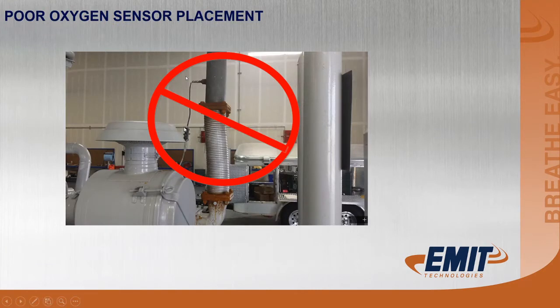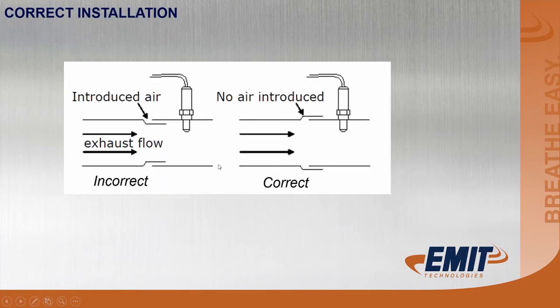Okay, again, this is a picture we showed previously. The reason for this is do not put the O2 sensors up here. There's cases where you can't help it and you just have to do it, but this was not a case. This could have been installed down here. Again, the galvanized from this will make this fail. This leaking, we'll see oxygen and it'll continually richen the engine up as the exhaust leaks through here.